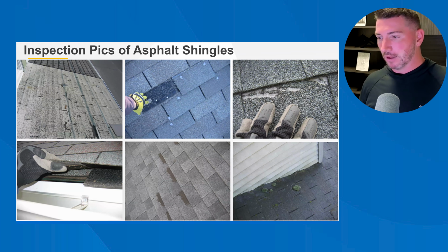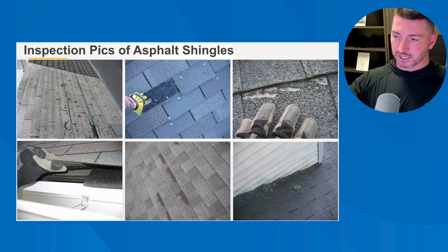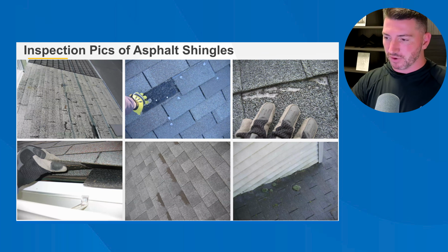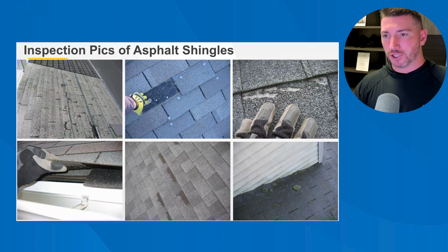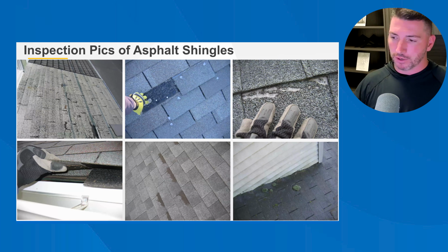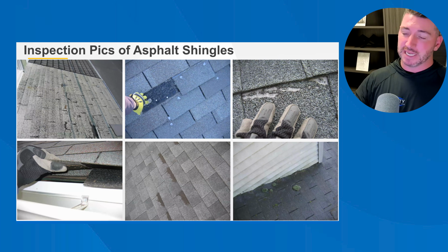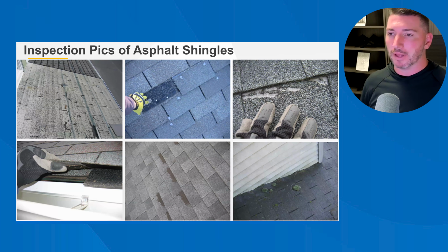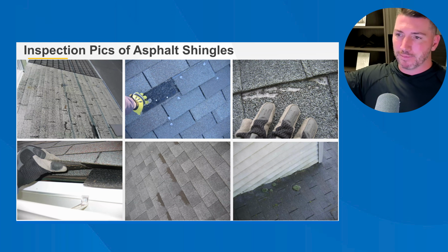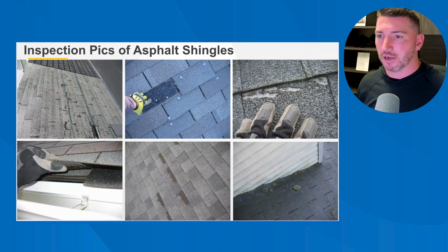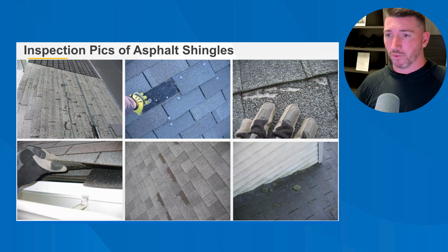Bottom left picture, that top layer is obviously the roof covering material. It's an asphalt composition 3-tab shingle. Underneath that, in the inspector's hand, he's got one layer of roofing material. And what I mean by that is every roof should have a starter strip installed at the lower edge. And it's a particular type of shingle. A lot of people will just, if it's a 3-tab roof, flip the 3 tabs upside down. But as you might imagine, when you start layering things on top of each other, at the headlaps, you have up to 3 layers of shingle in a normal roof installation with 1 layer of shingles.